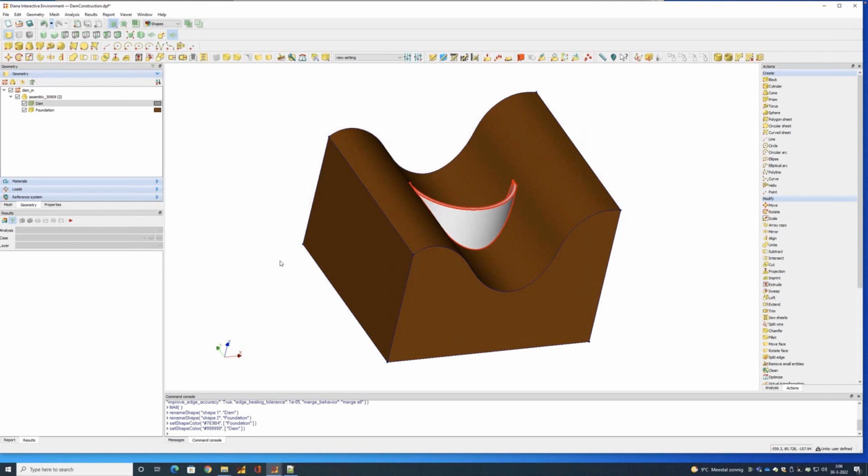So what we need to do now is basically to divide our dam into segments, or into cantilever segments, let's say. To do that, we are going to use a set of vertical planes, which will be passing through the center of the circle, defining the curved surface of the dam. So having said that, we need to create some tool geometry in order to achieve this operation.